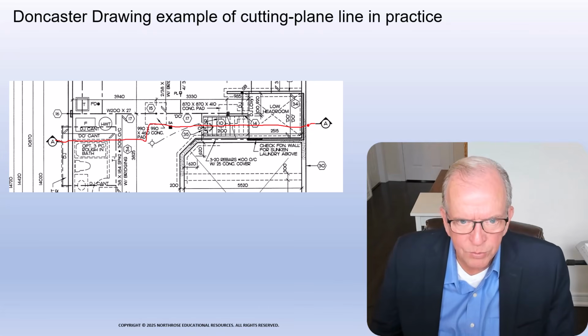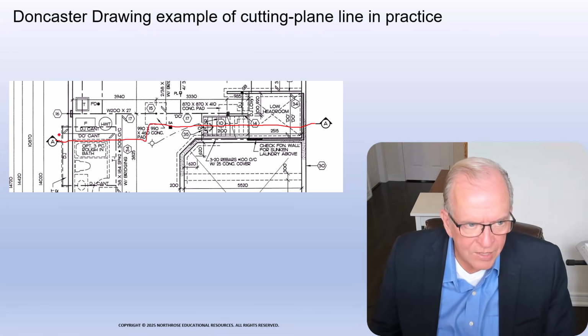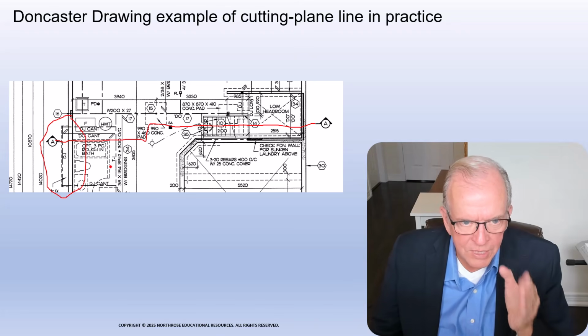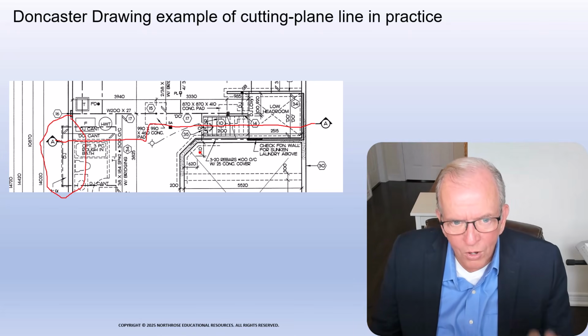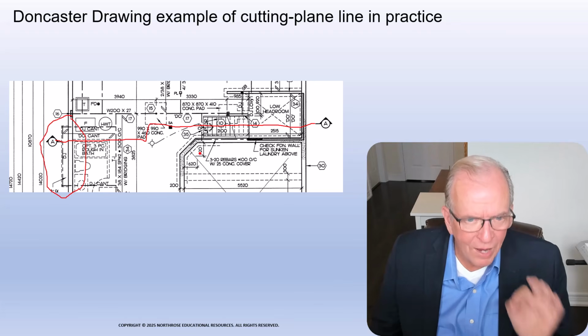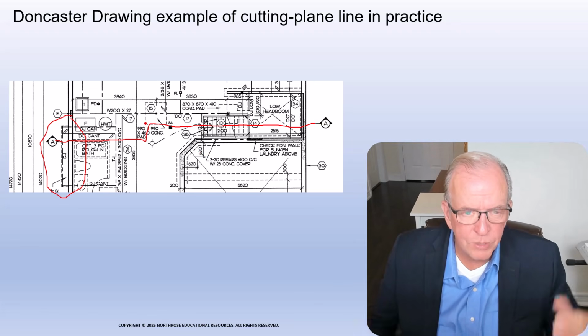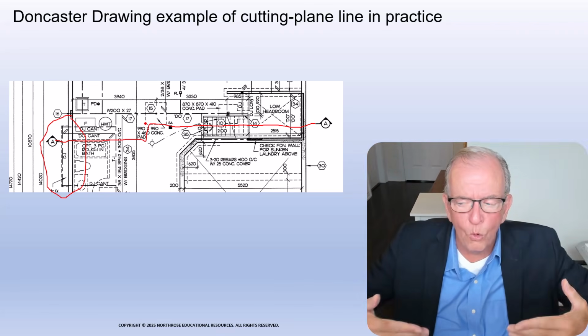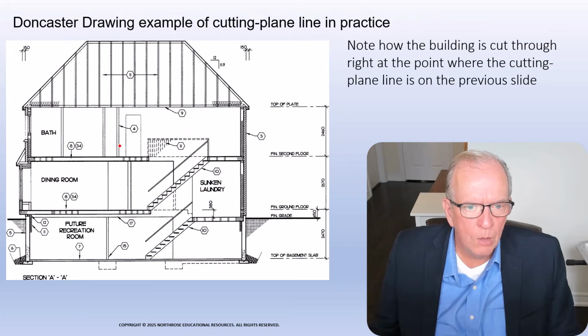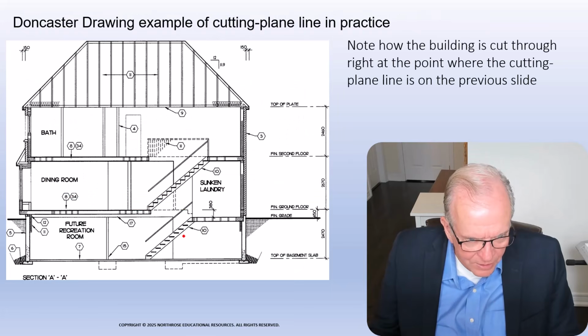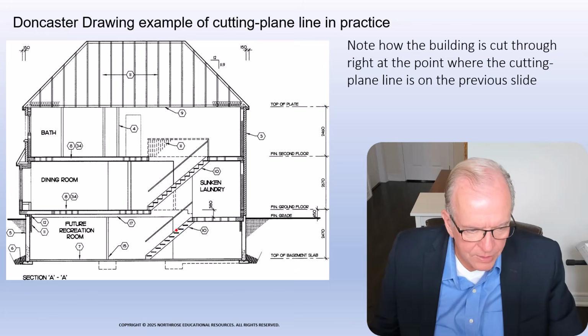So it's cutting through where the stairs is, and it's cutting through where this box window is, which is cantilevered out, so you can see inside the structure. And it's not only cutting through on the basement, on every floor plan. On every floor plan, you're going to see this above. So this is like a section through the whole house where you can see through the whole house and what it looks like. So I can see where the stairs is here, right?